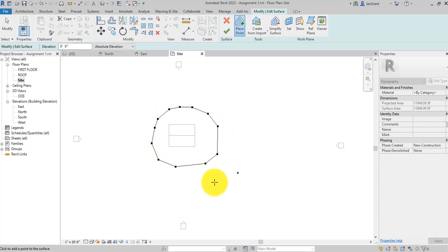And you'll see that, okay, now I've started this 0 elevation. Now, don't go out of the sketch mode. Just go right up here to the elevation and type in -2. Well, -2 is going to be like -2 feet. And so I'm going to start clicking here around what I just drew to get to the next elevation, which will be down from level 0.